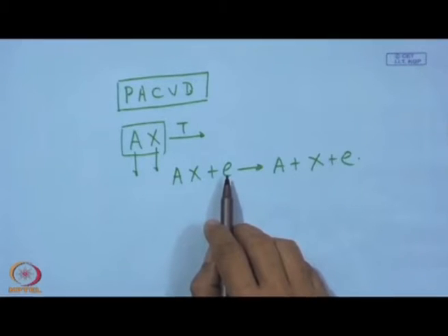That means, inside the CVD chamber we must have sufficient electron, and during its course of movement towards the anode, it may interact with the neutral molecules of the gases, and thereby finally these gases will be ionized, and in this ionic state their reactivity will be much more stronger, vigorous, and that will be facilitated because of this ionic state.